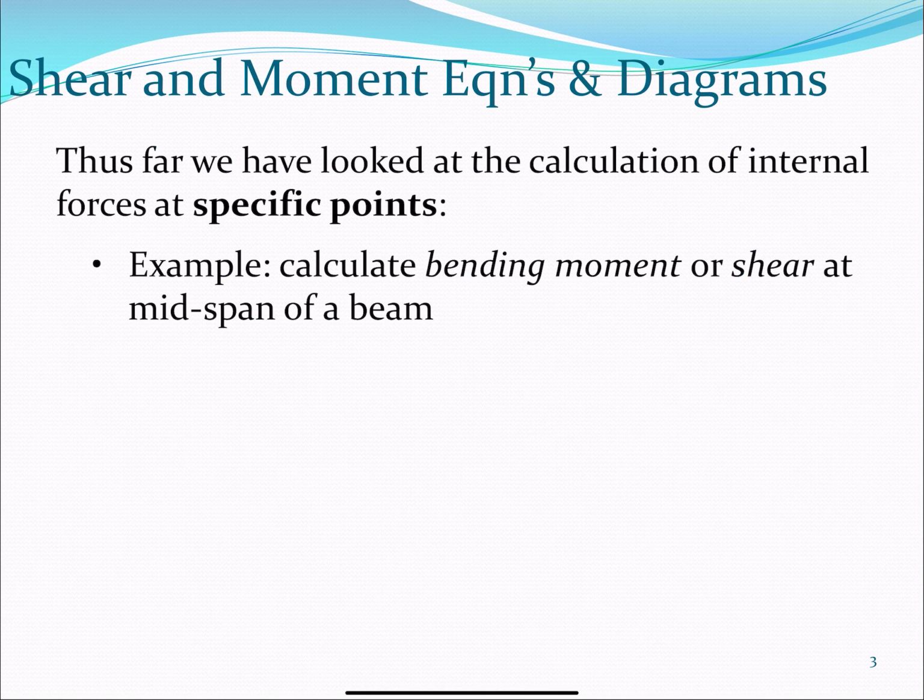So shear and moment equations and diagrams. Thus far we have looked at the calculation of internal forces at specific points. That's what we have been doing. For example, we calculate the bending moment or the shear at the mid-span of a beam. So we have a beam like this, and then some load over here, and then we decide to cut, and then investigate what the forces are. This is A, B. What are the internal forces at point C?